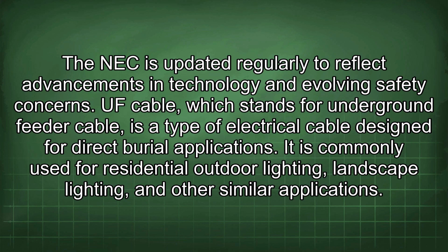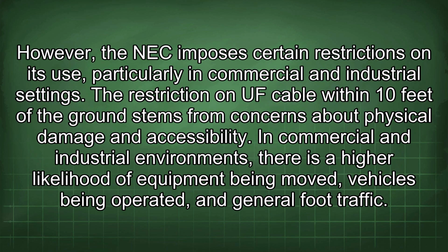UF cable, which stands for underground feeder cable, is a type of electrical cable designed for direct burial applications. It is commonly used for residential outdoor lighting, landscape lighting, and other similar applications. However, the NEC imposes certain restrictions on its use, particularly in commercial and industrial settings.